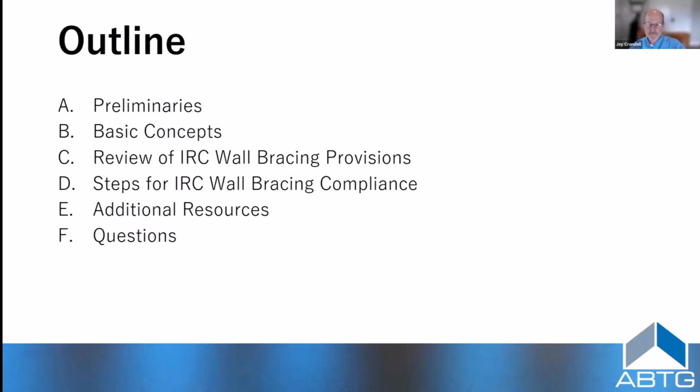And on the moisture side, also the provisions that are in the code related to insulation ratios, and how you determine your U factors or your thermal performance while also balancing the moisture performance. There are new vapor control provisions in the code that I've been deeply involved with. So all of this stuff actually fits together. Decisions you make on your structure and how to do it actually affect other performance attributes that you need to be concerned about, like moisture control.